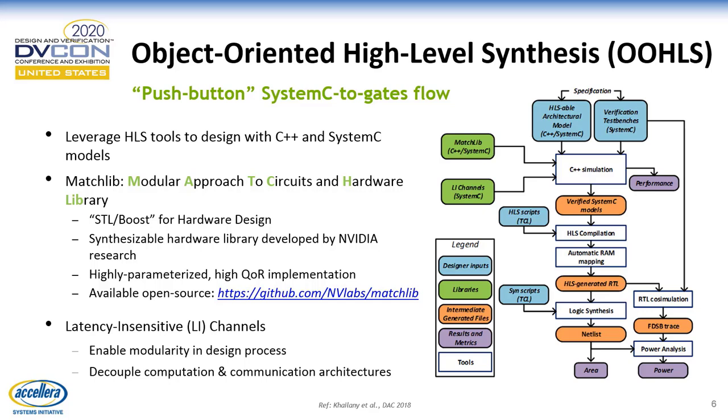The other key aspect of high-level synthesis-based methodology is that the latency or the schedule of the pipelining is determined during the high-level synthesis process and is not available at the design time. As a result, it is important to decouple the design of different blocks and their timing dependencies during the design process. For this, we used a latency-insensitive channel-based approach, which enabled modularity by decoupling the computation and communication in the architectures.